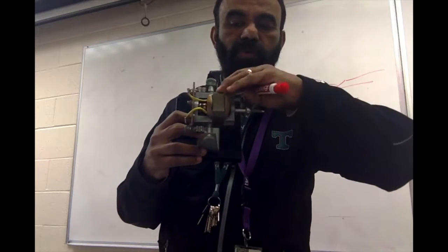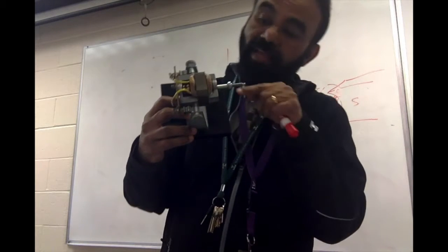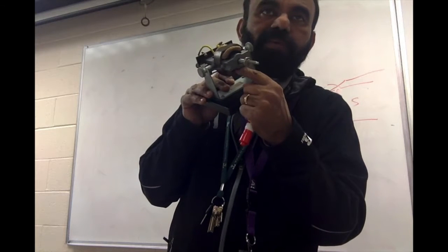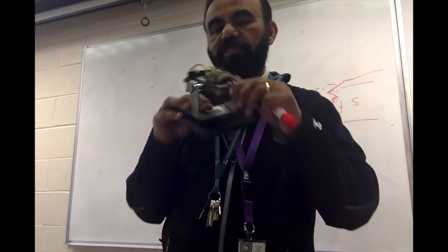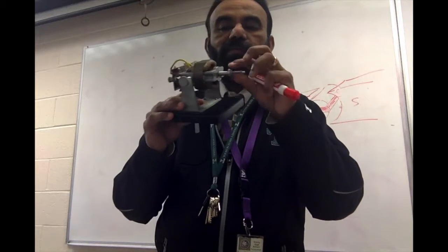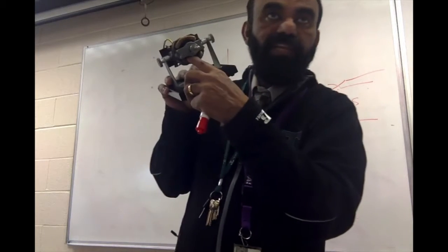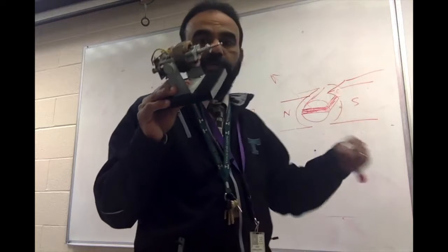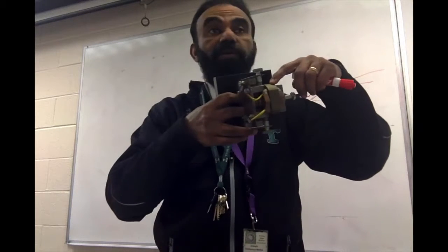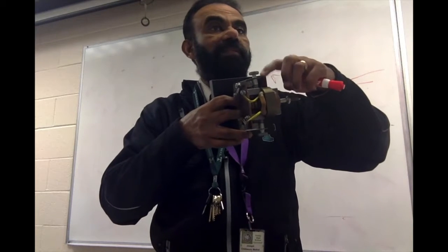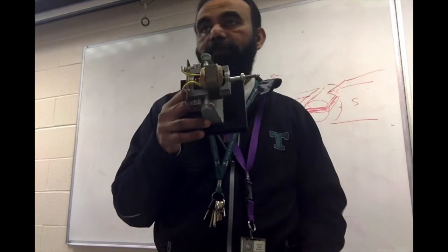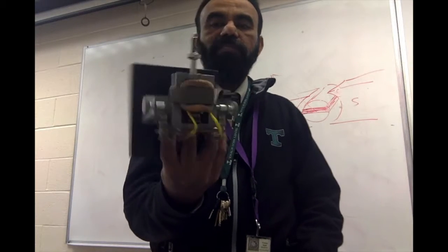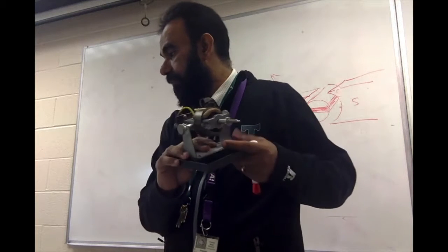There are two cores here. One is this one, which produces the magnetic field, and there is a core on which the wires are wound. It's hard to see it. Only when you take this out, you will be able to see it. Okay, so the winding is done on a core, but this core is different. But you can see they're all laminated. They're all laminated because you don't want eddy current losses in them. Okay, so I'll pass this around and you can have a look at it.